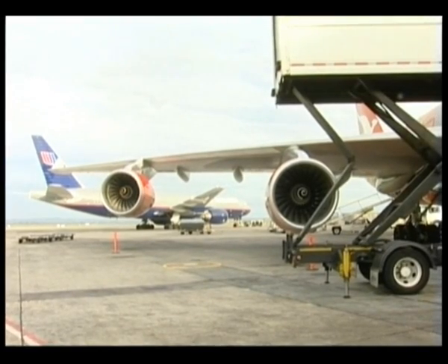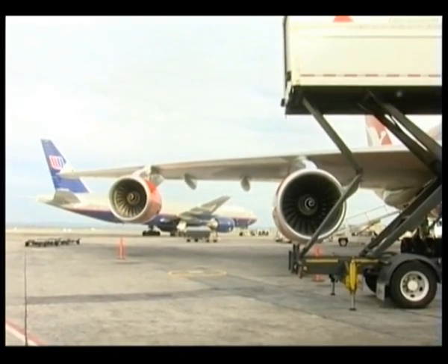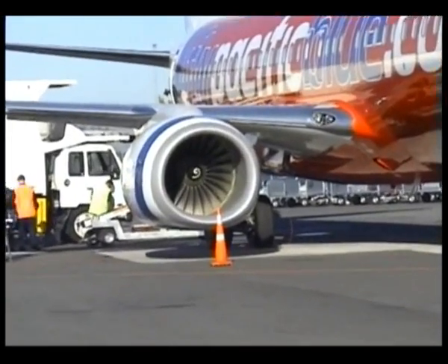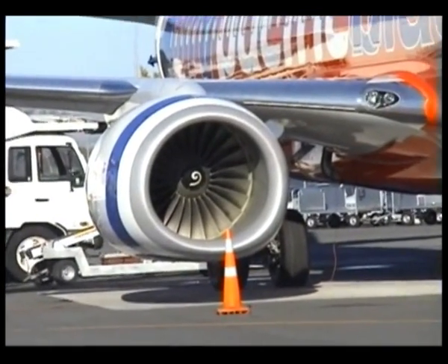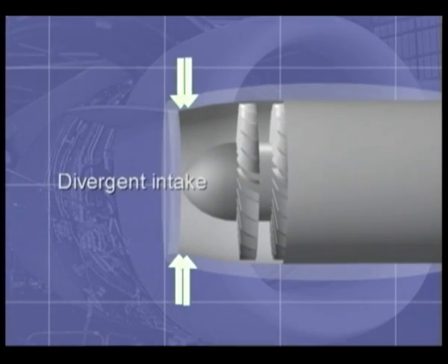Most civilian aircraft fly at subsonic speeds, and they, unlike supersonic aircraft that require a center body or wedge-type converging intake duct, require a divergent intake duct to decelerate the free stream flow and increase the pressure.